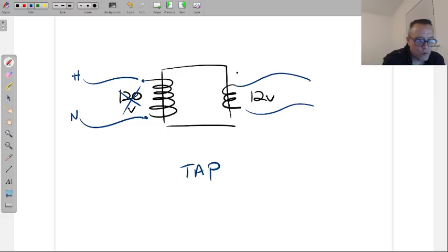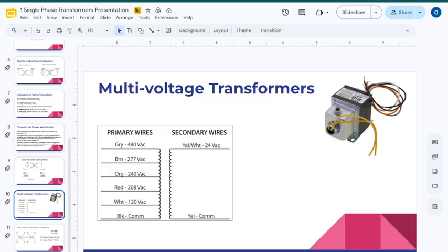These are great for repair. You carry these on the van for service, and you walk into a building, you're like, what voltage is going to these lights? Oh, 277. Great. This one could be connected to 277. What voltage is connected to those lights? 120. Great. I can use this one for that. So it's just any voltage that the lights are connected to or that the building has.